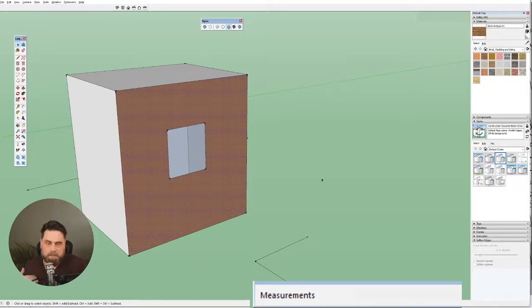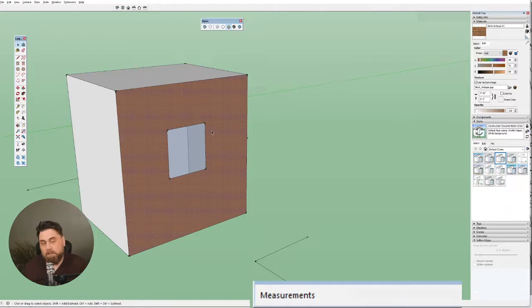So it gets rid of the actual texture image, and then we'll just go with the color instead. So if you want to be a little more nondescript when you're presenting something and don't want to bog the customer down with specifics on material choices just yet, and you're still focused on just the flow and the shape and all that stuff, then you can turn off textures with shaded mode.